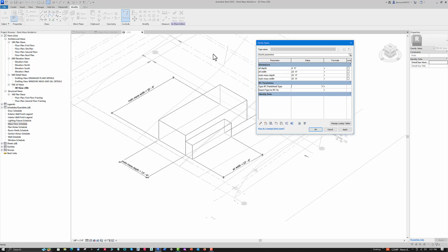And I have a wall thickness that I'm going to have to contend with. And I know that it's going to be a 2x6 wood frame with a siding on it of some type, a thin siding on it. And I'm going to allow 6 inches for that. If I was doing brick, by the way, I'd probably allow 12, but I'm not doing brick. I am doing wood frame, so I'm going to have to take off another foot on each side.